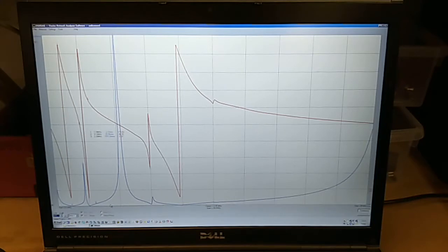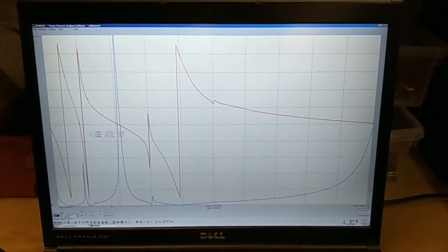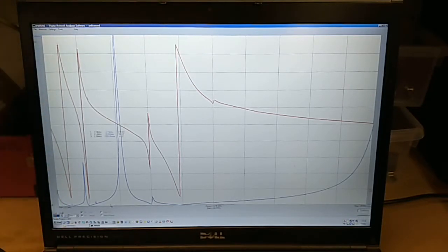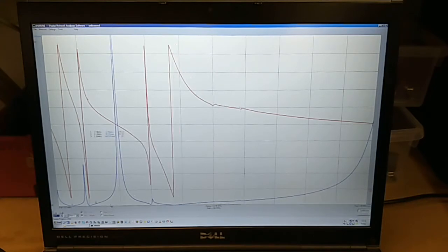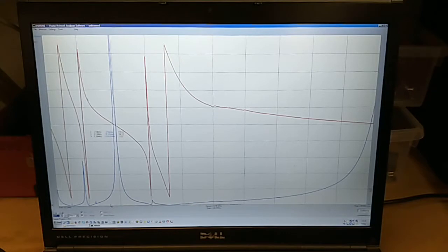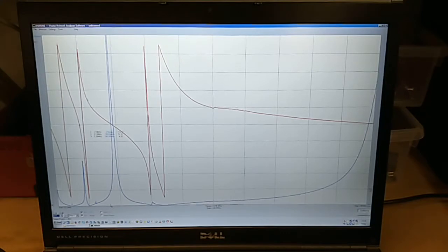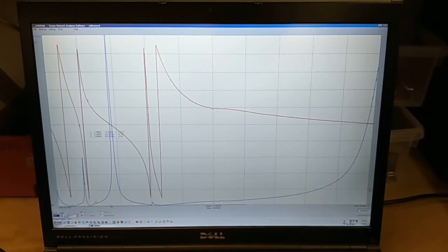Just pause it there for a second just to go over that again. In this particular flat coil arrangement, as we spoke of before, the wire length in quarter wave mode very much determines this phase transition, and that's why that is not changing and that phase transition is not moving. Also the tank circuit resonating primarily with the primary is also not really changing at this time. So we're going to carry on increasing the primary tuning capacitor.